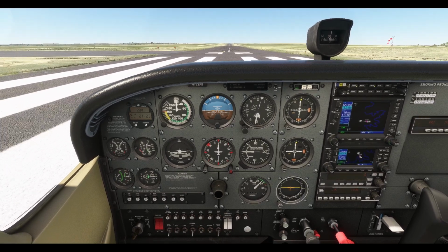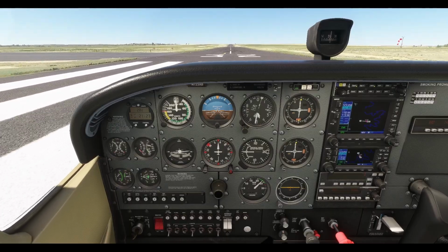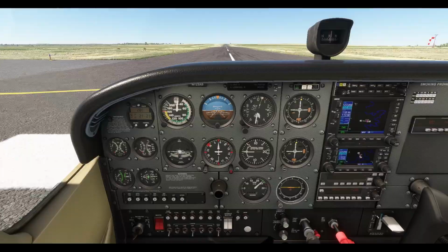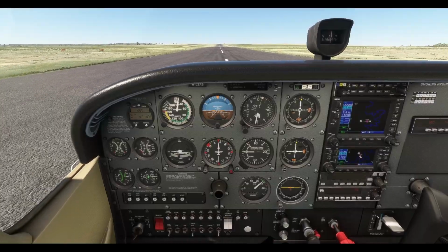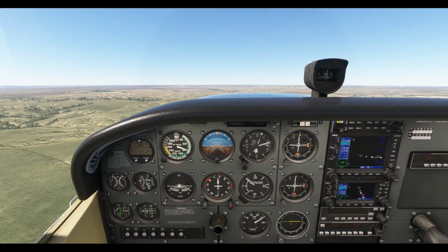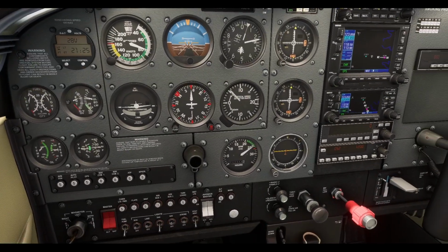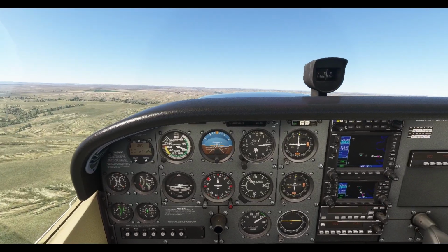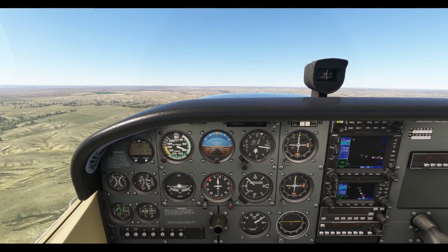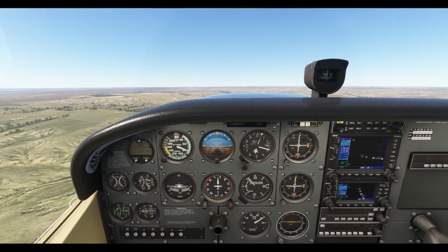As the airplane moves forward, the relative wind changes so that the angle of attack of the propeller decreases. The engine RPM begins to slowly increase. Since we are not achieving maximum RPM on takeoff and climb, we can safely leave the engine at full throttle. Of course, if your POH has something different, always follow the procedures prescribed by the manufacturer.